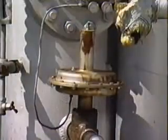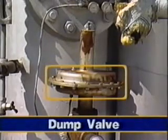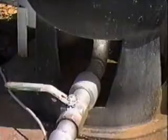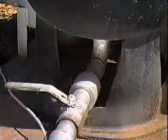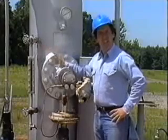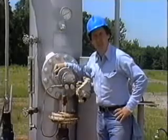The liquid level control valve, or dump valve, is located near the bottom of the tank. As the liquid level rises in the tank, the liquid level controller opens the liquid level control valve to maintain the proper liquid level within the tank. At the bottom of the vessel, a drain is available for cleaning out the solid debris which accumulates. Gauges and sight glasses on the vessel aid the operator in monitoring pressure and fluid levels within the separator.